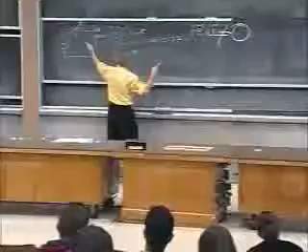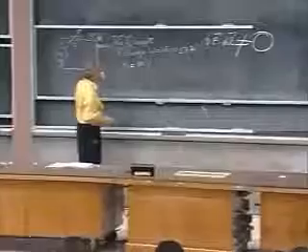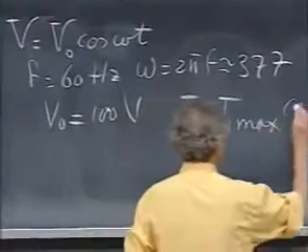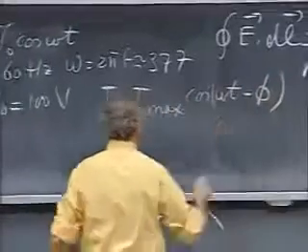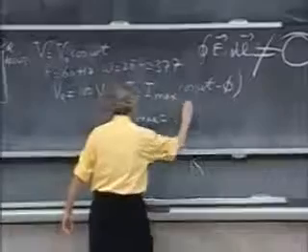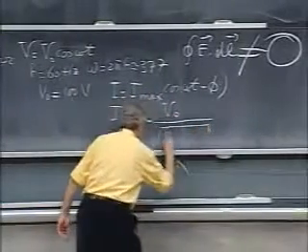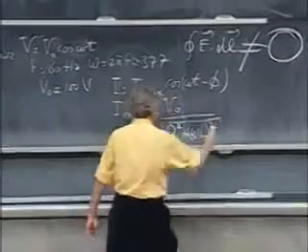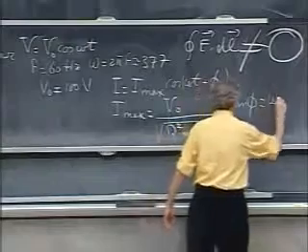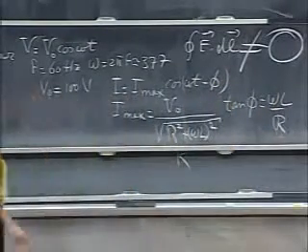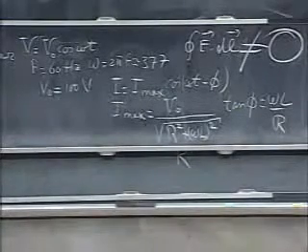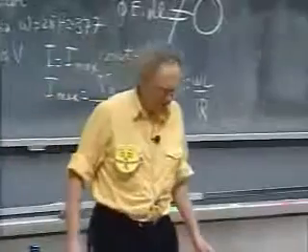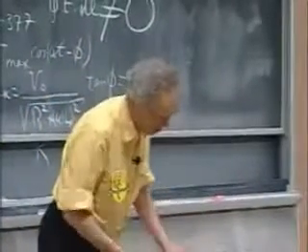And the answer then is that the current that is going to flow as a result of this variable voltage, that current I, is a maximum value times the cosine of omega t minus phi, that the maximum current itself is V0 divided by the square root of R squared plus omega L squared, and that the tangent of phi is omega L divided by R. I spent quite some time on this during one of my lectures. And so the maximum current that will flow depends on omega and depends on L, the self-inductance, and of course on the resistor as well.